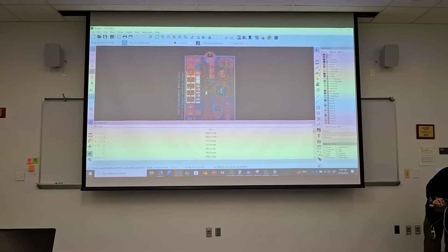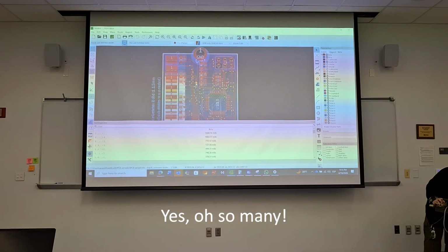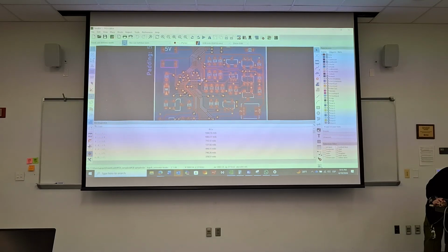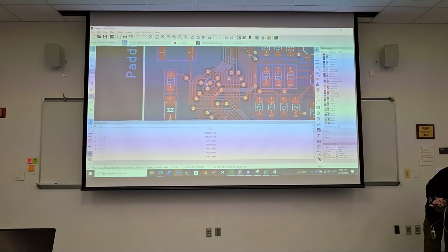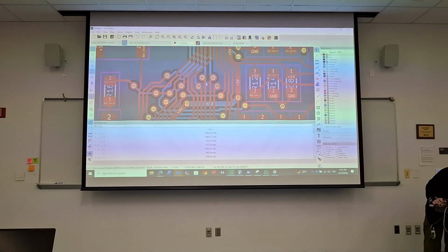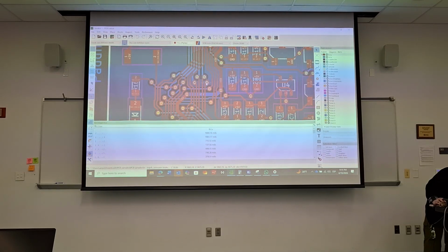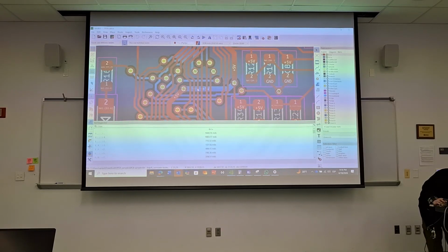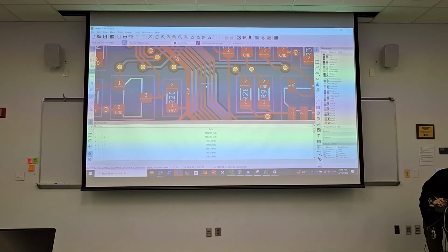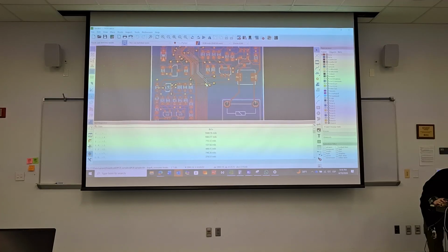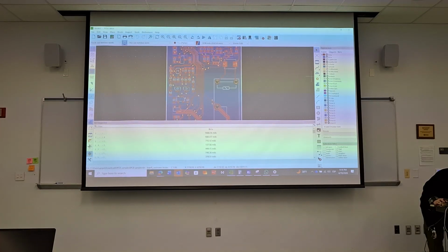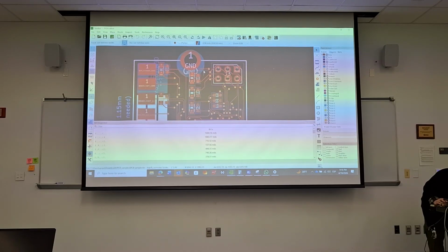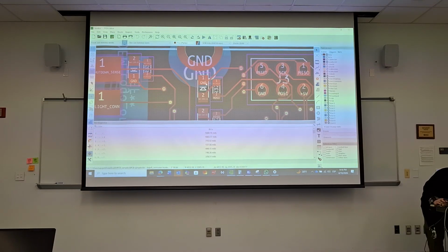Have you had many issues with this board? Yes. Oh, so many. Yeah, I would add more ground layers. That's where I would start. Also, these via transitions need, well, you have good grounding, or you've grounded these, but ground traces are something I would avoid. I would start with a ground pour on this layer, because right now it's just traces, not a ground pour. It should help.